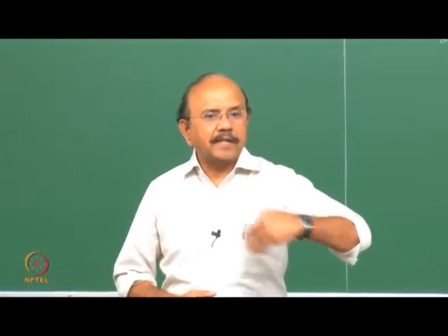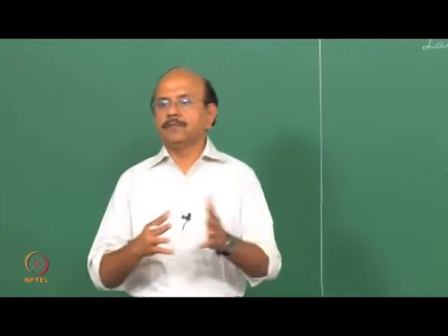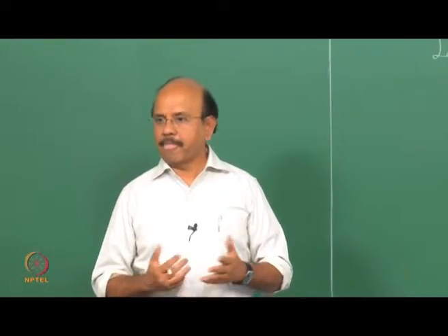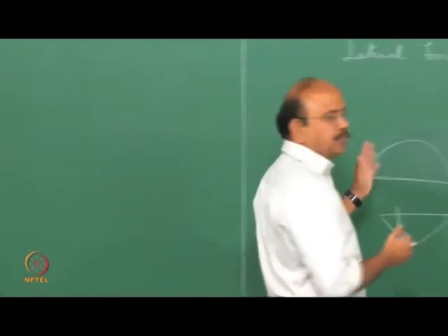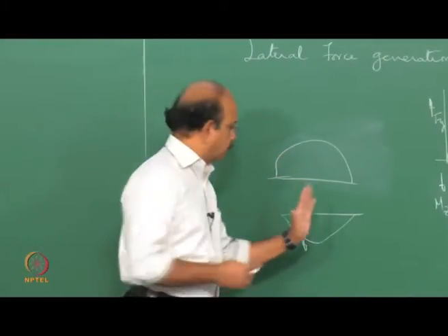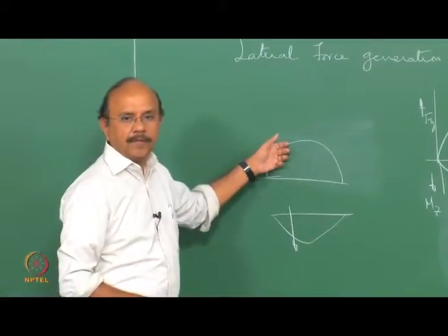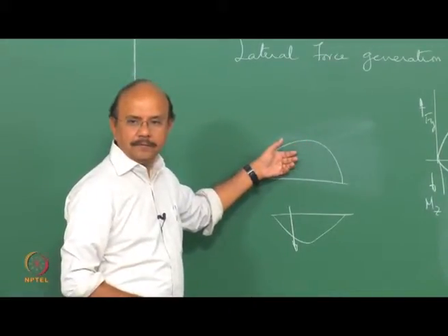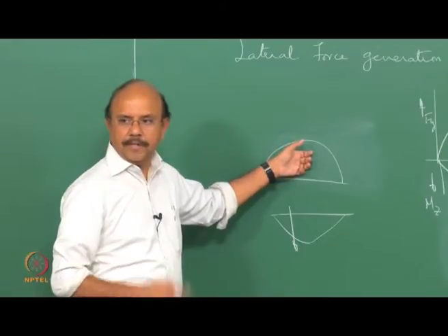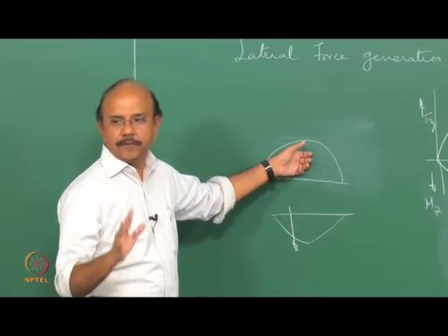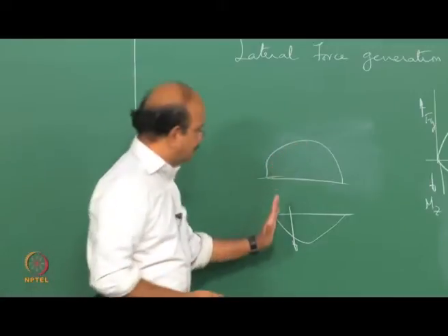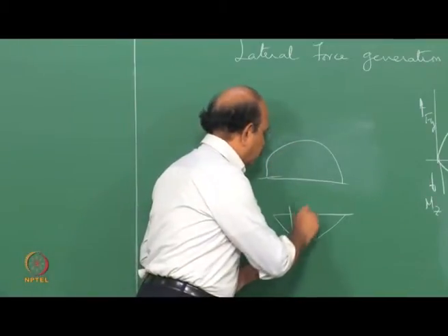Now, imagine that slowly the bristles are going to slip. When it slips, what happens? It reaches a maximum value which is mu into qz, right? So all of them are going to assume the value of mu qz, and this being almost symmetric, though not exactly, this resultant force is now going to move towards the center.